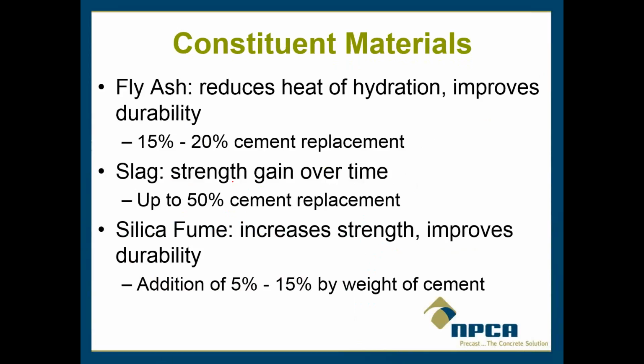So back to the SCM, fly ash can be used to reduce the heat of hydration and improve durability. Slag improves strength over time, and silica fume is extremely fine, and that helps increase strength and durability and reduces permeability, I believe, too.